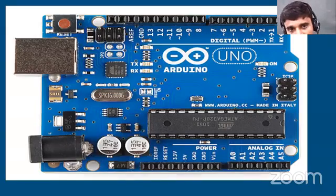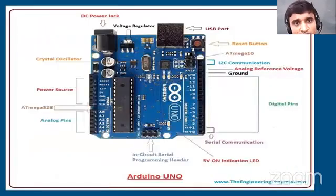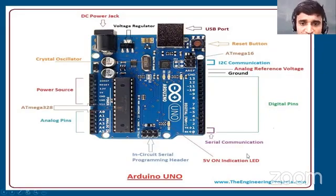You connect the USB, give power supply to the Arduino board, and transmit your code into the circuitry, and then your code executes easily. After that, you connect with the computer and your board works as planned in the code. This is the pin diagram of the board. For serial communication with a sensor, you can use pins 0 and 1, which are transmit and receive for serial communication.